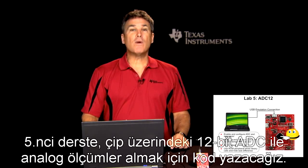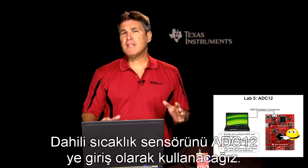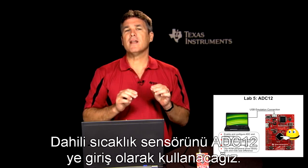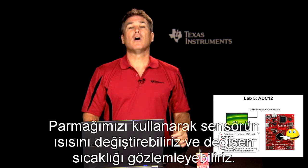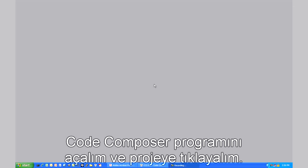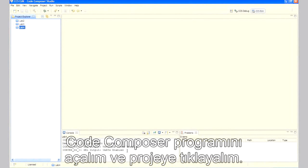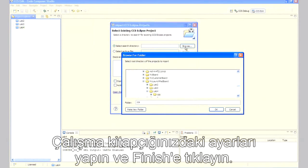In Lab 5, you'll write code to make measurements with the on-chip 12-bit analog to digital converter. To keep things simple, you'll use the internal temperature sensor as an input to the ADC12. You can then use your finger to warm the microcontroller on the LaunchPad board to see the temperature change. In Lab 5 Step 1, we've already created the Lab 5 project for you with an empty main.c, a startup file, and all necessary project and build options set. Maximize Code Composer and click Project, Import Existing CCS Eclipse Project. Make the settings shown below in the workbook and click Finish.